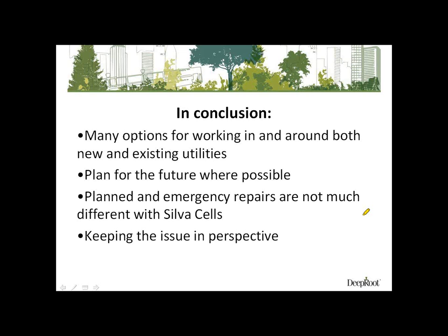When we do a stormwater system, typically we'll use a different soil mix: 80% sand, 20% compost mix, and a Western Washington rain garden mix or bioretention mix. We have some different numbers on what each Silva Cell can store as far as water volume. I can't think of the number off the top of my head. Maybe Lita, you can help me out with that.